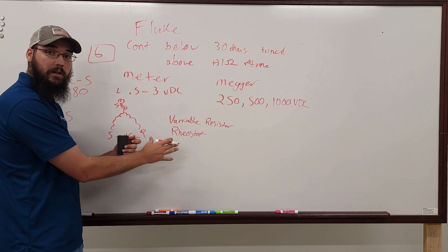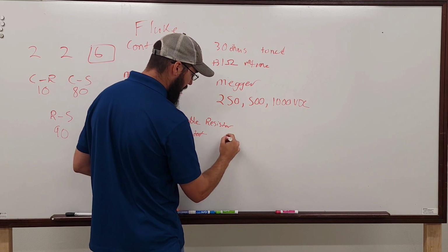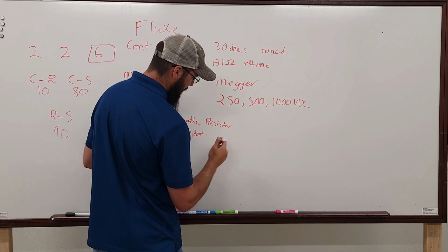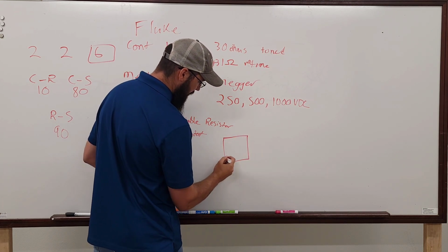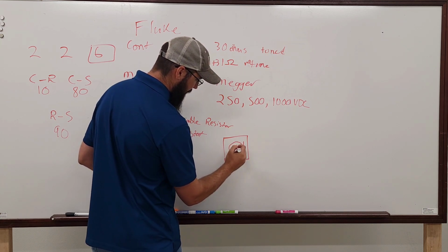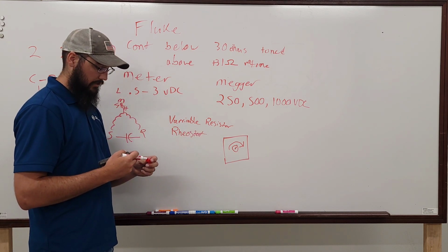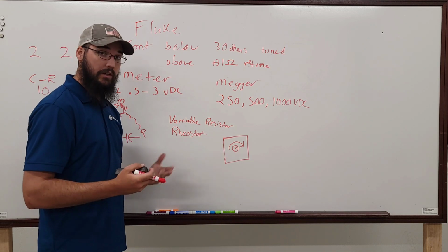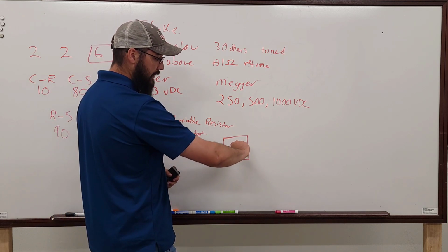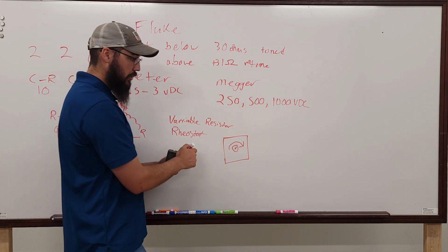So you can take a single speed motor, and there's nothing fancy to this. It's literally just a box on the side. It'll have a little turn dial. You see these on exhaust fans a lot, and on fan power boxes. Those are the two most common. You can put these on split system air handlers. And so you adjust this, and whenever you're adjusting the speed up, your ohms go down.